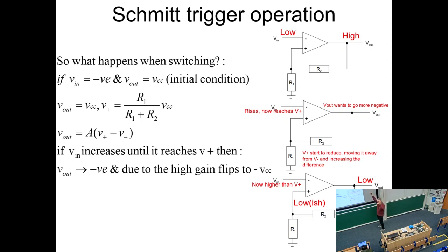And then when the square wave goes down with the noise on it, it'll trigger this level shift again, and you'll get the other level out. So you'll end up with a replication of the square wave that's coming in, but without the noise. So not filtering it as such, you're regenerating it. You're making a complete new copy of it without all the noisy stuff.